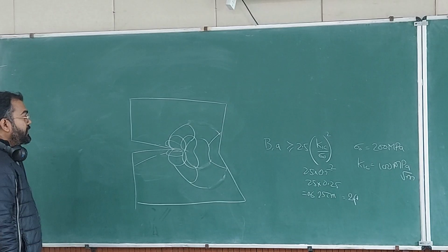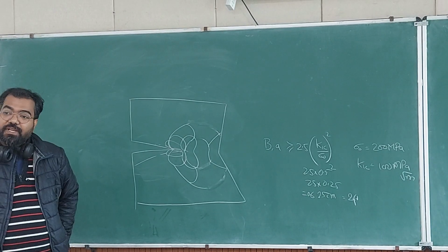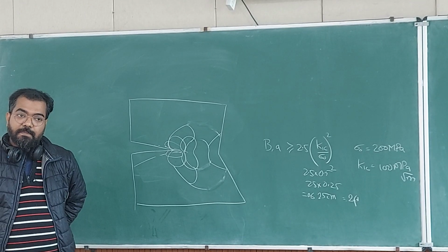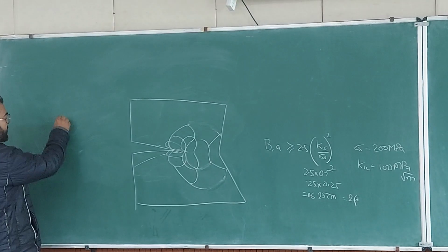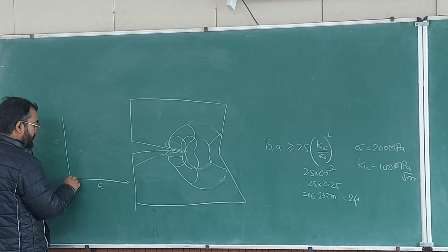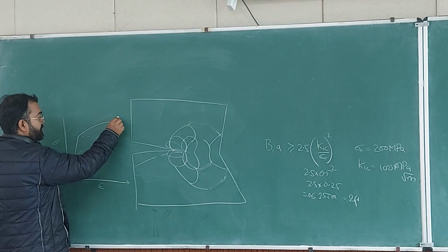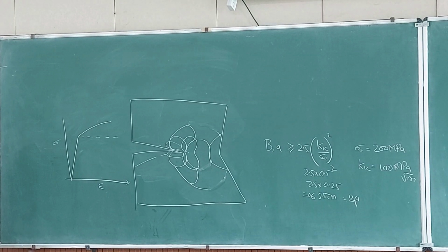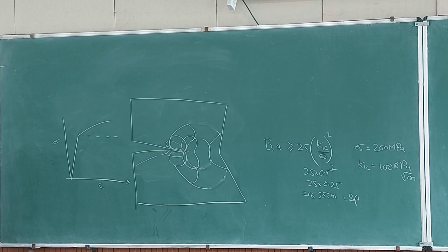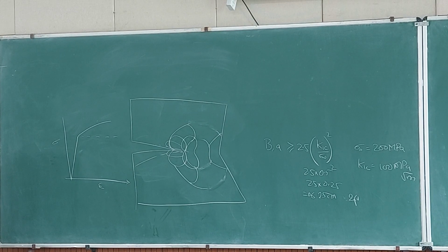It will grow, but it will not move. Okay. And what will happen if we have strain hardening material? So the material we usually have in metallic conditions. So we don't have ideal plasticity, we have strain hardening. So what do you think, for strain hardening material, the plastic zone size will increase or decrease? Decrease. It will decrease.